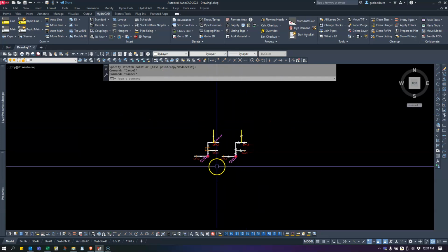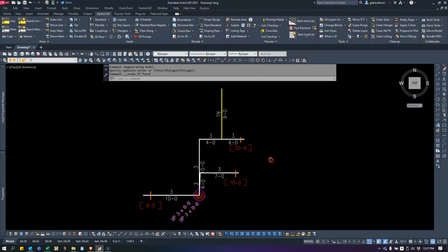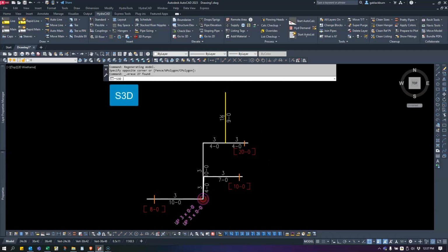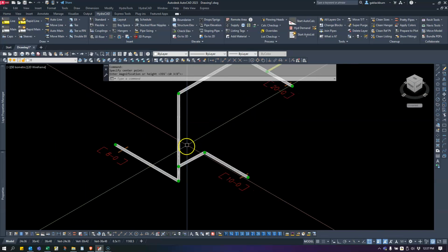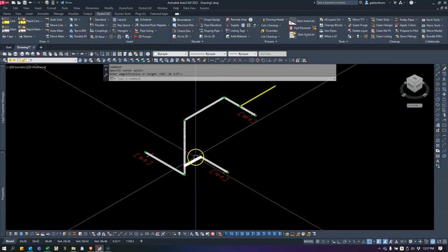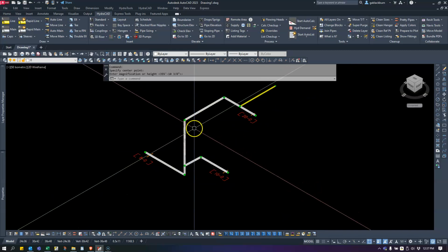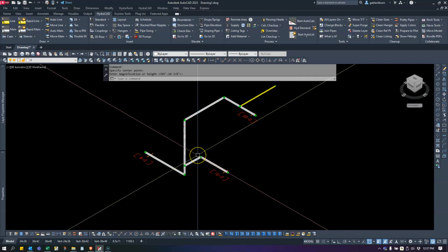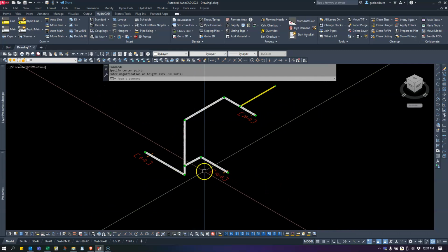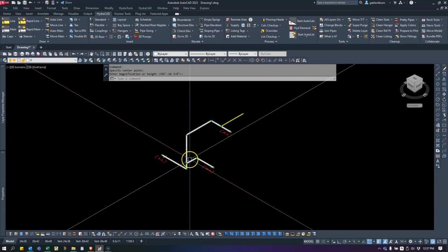Okay. Now I want to do a quick test here, and I want to raise it to 3D and just see what we get when we do this. So I will S3D and let's see what happens. Let's just verify that it gave us our stacked riser nipple here. So again, for all intents and purposes, even though this is rotated by 2 degrees, it's going to give you what it's going to look close enough to what you want. And again, I believe a 2-degree angle is the minimum that you need to rotate it. Less than 2 degrees has problems. So there we go. We're all set for this part.